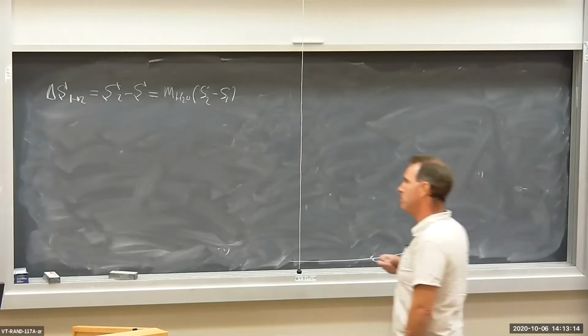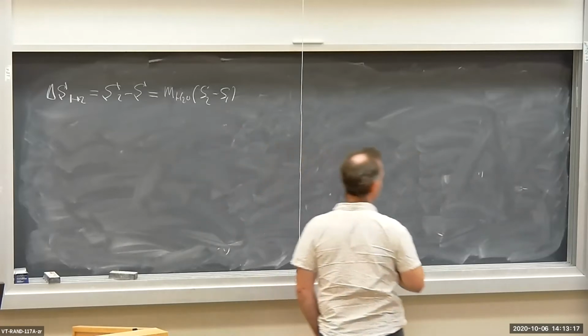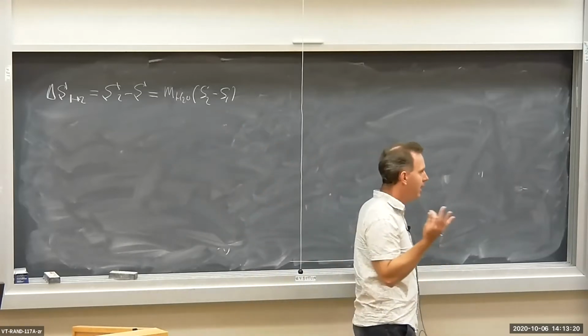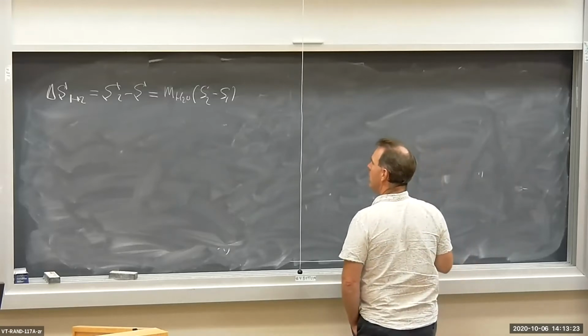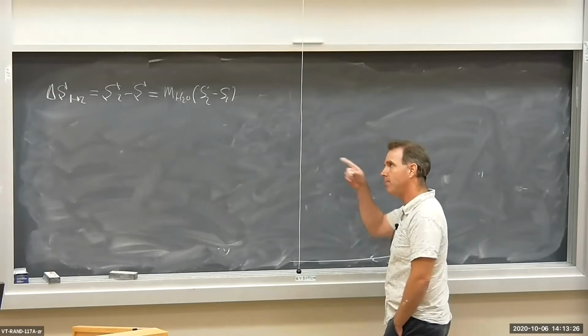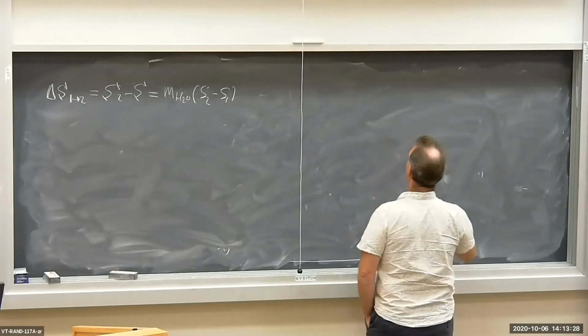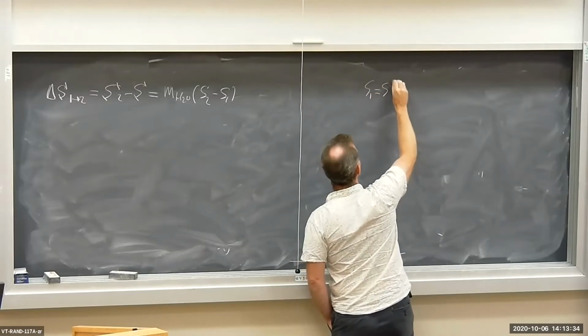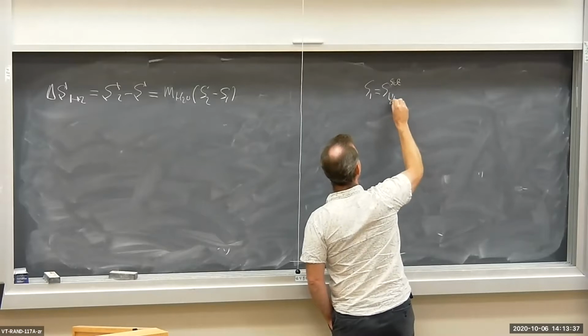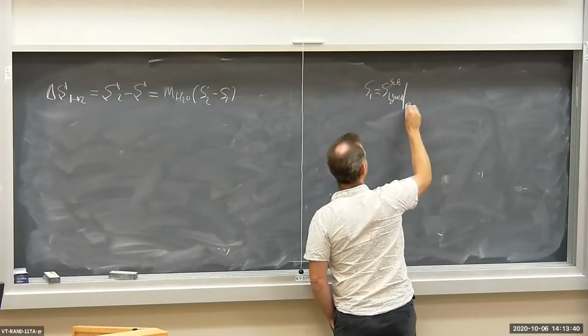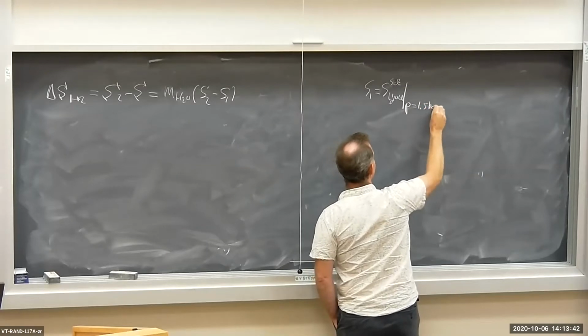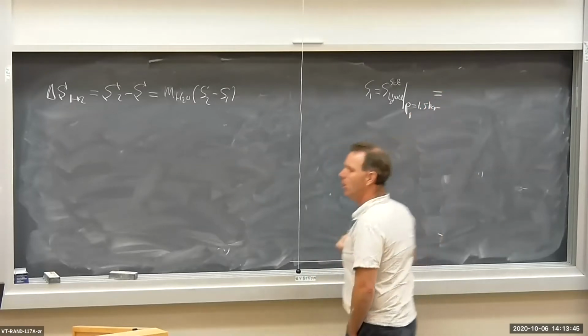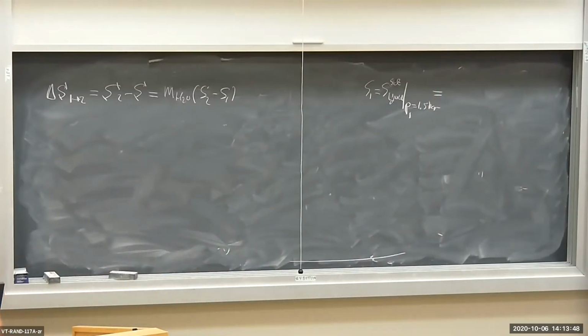Let's look up entropy, specific entropy for the H2O at the initial state. I know the pressure and I know the quality. It's a saturated liquid, the quality is 0. So I can go to a saturation table and pull out the specific entropy at state 1. So S1 is S of a saturated liquid evaluated at a pressure of 1.5 bar. That's the pressure at state 1, okay? So let's go to our notes here, and let's look up the pressure saturation tables.